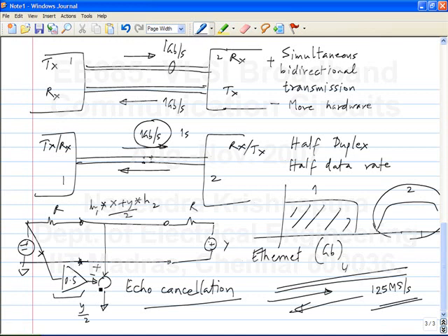And that is what is done in a high speed system. So you can do full duplex on the same pair of wires, but the challenge is echo cancellation. This is a big challenge because the signal on this side is of the same magnitude as the signal on this side. Now when y comes here over a long transmission line, y has become small, but x is still the full size signal. So in fact your interfering signal can be much larger than the signal that you want to receive.